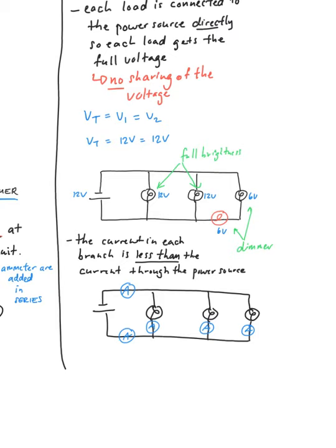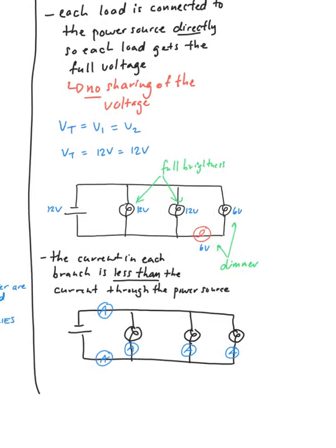So now if I was to take the measured readings of the amperes in each of the sections of this particular circuit, if I had 3 amps flowing out of the battery, then when it hits this section here and it can branch, the current can either flow in this direction towards this light bulb, or continue on towards this light bulb, or even continue on towards this light bulb. So when I actually measure the current that is flowing through this portion, I may only actually get 1 amp rather than the full 3.